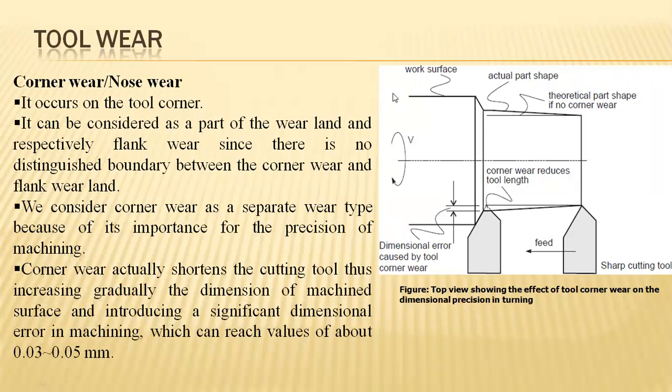See, normally this is the work part containing the step cutting in the lathe machine process, removing excess material. So this is the original dimension, and this is the dimension to be achieved, and the excess material needs to be removed by considering a feed rate and the interaction of the tool, and this is the tool, a sharp cutting tool. The sharp edge comes into contact, this is the wedge shape, and the corner elevates the chips towards removal from the work part.